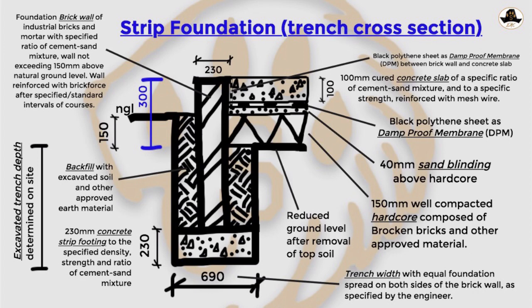It's for that engineering. It's basically the forces and all those things, the dead loads, the forces, how they affect the trench, rather the foundation in the trench. That effect has to do with some forces and the weight. So that's catered for when you make it 3 times the thickness of the wall.